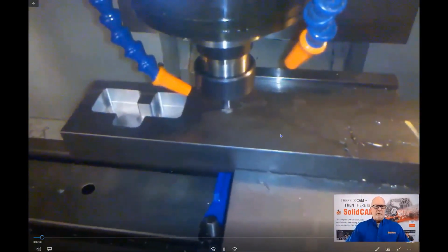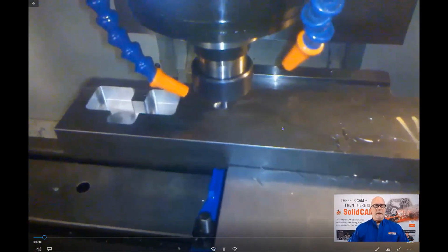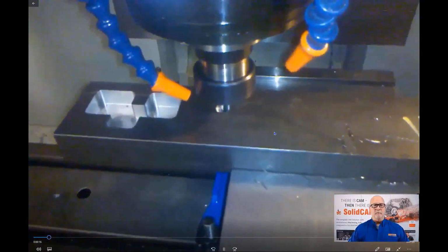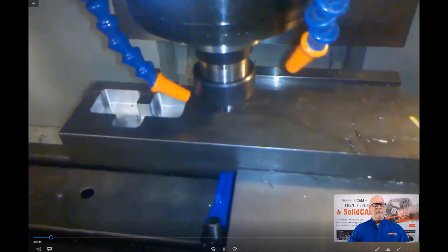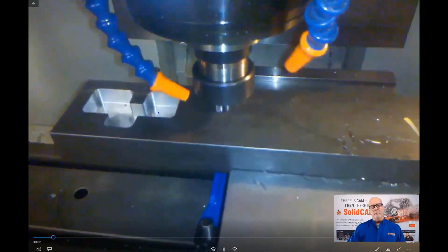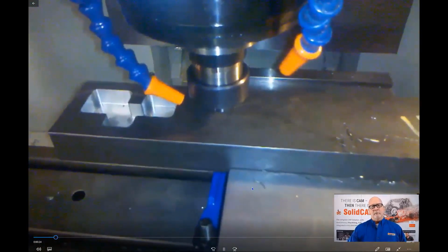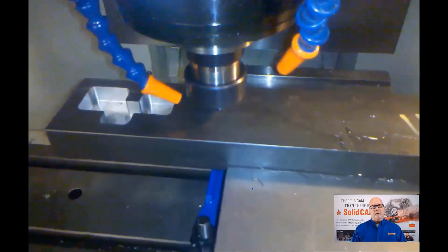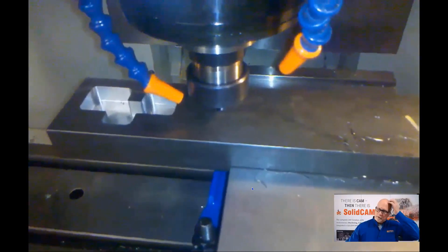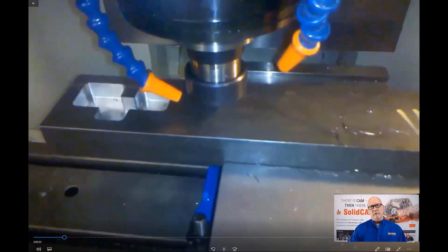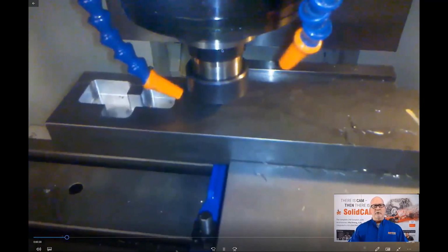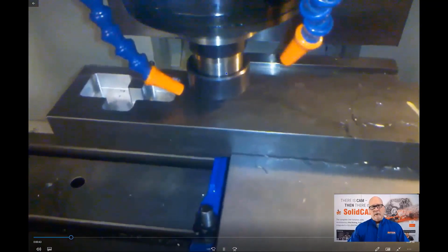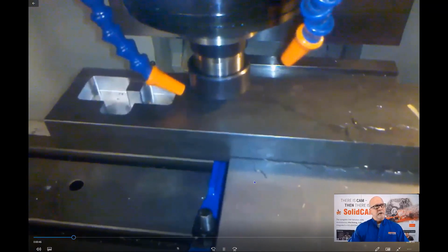Now, this is one of our customers up in Colorado, and they had a Haas TM2, a tool room, open bed tool room machine. They were cutting pockets very similar to this in their parts that are 1 inch deep. And they're using a 3/8 inch OSG exocarb cutter, pretty good cutter. But they were only getting one pocket per tool, okay? And that's because this machine is pretty rickety. It's not super stable. This is only a 4,000 RPM spindle, and the controller could only manage about 50 inches a minute before it started getting into data saturation.